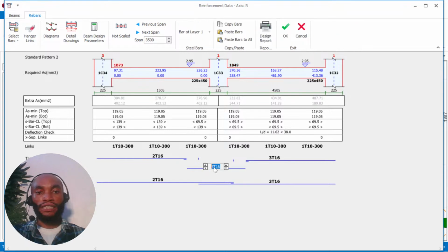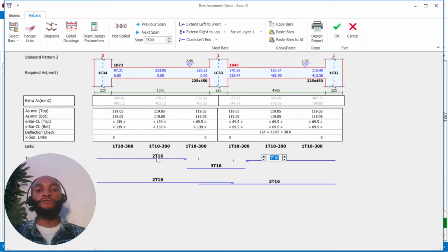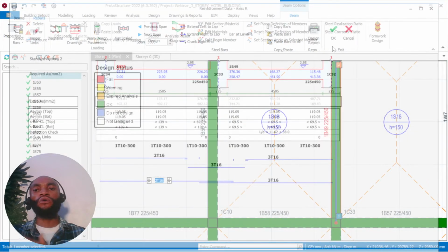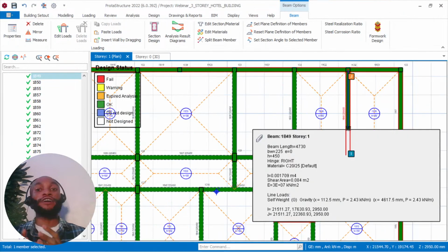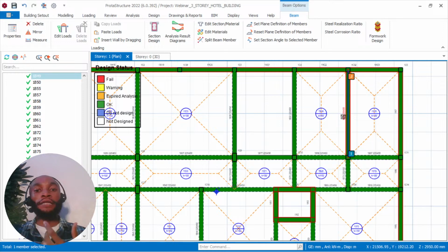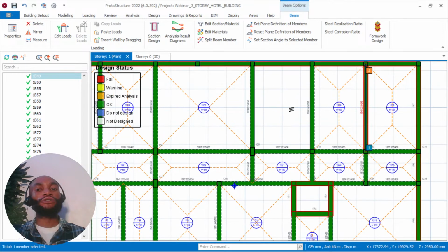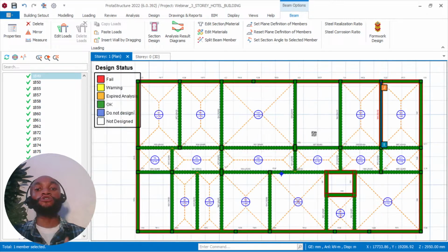And also save cost here on these 2 spans by removing 1 bar, and also 1 bar here, and you can see that it is perfectly okay too. So with this now, come and say okay here. Basically, iterative design looks very boring. It is not what you enjoy, but it is the most important part of your design, because you are trying to reduce the cost and check what the software has given to you. So make sure you spend time on that.